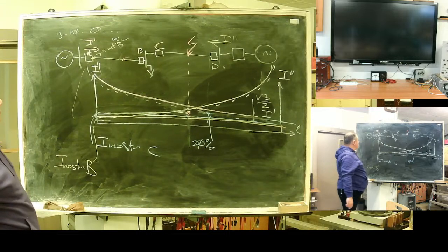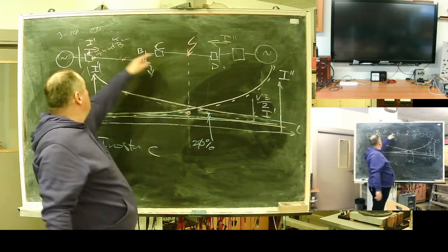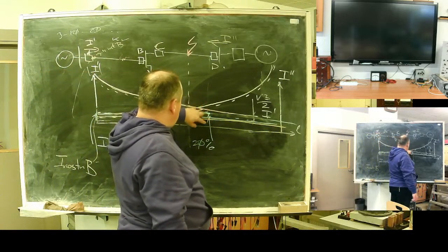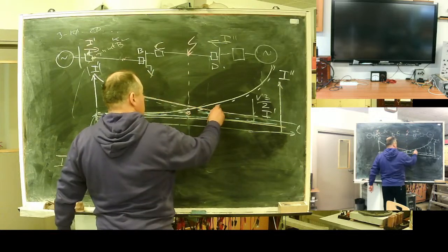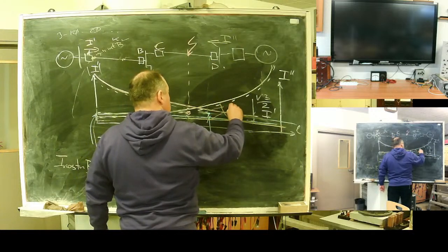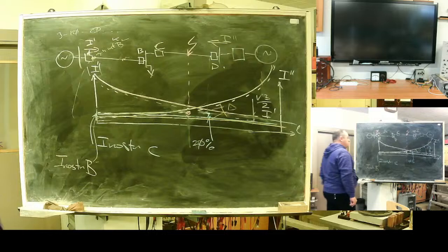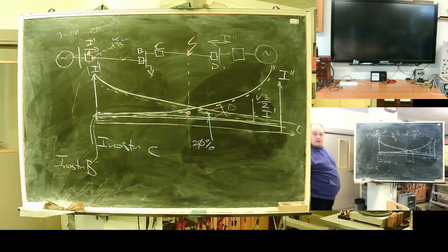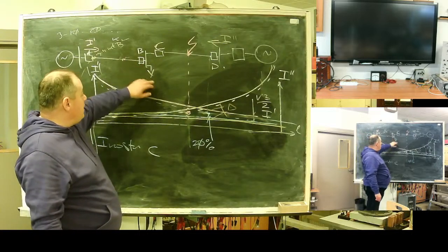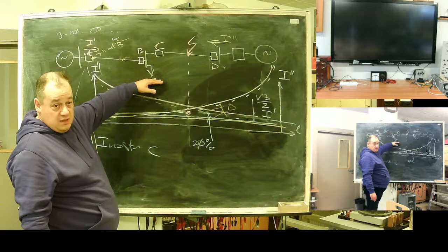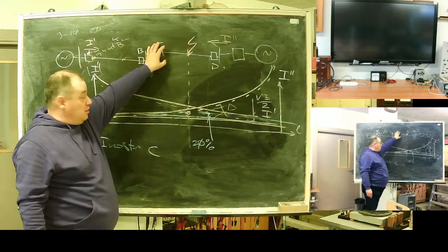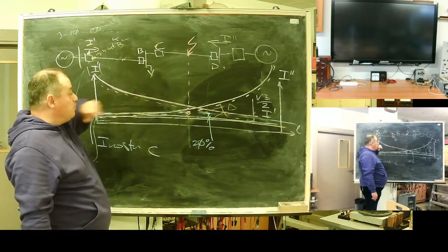What will the B relay do in case of this fault? Red current, red current, red current. Oh yeah, red current is well, you see this? Red current is above a trip line. So B will operate. You see? B will operate and kill this customer. It's not good. Only this switch should operate. This customer should remain. This is not good.